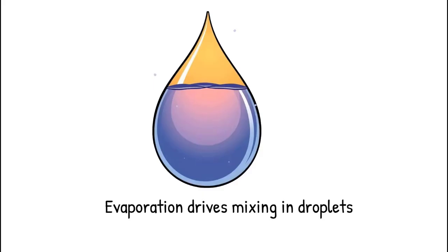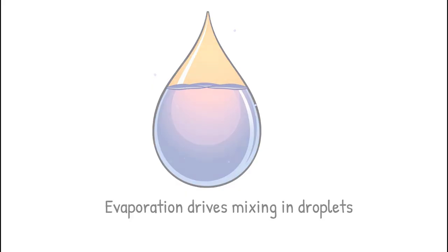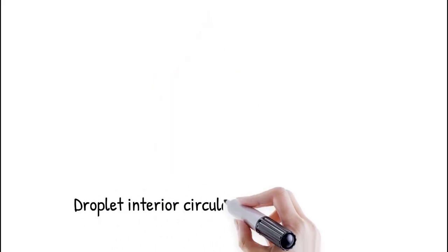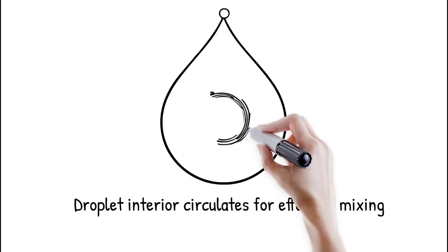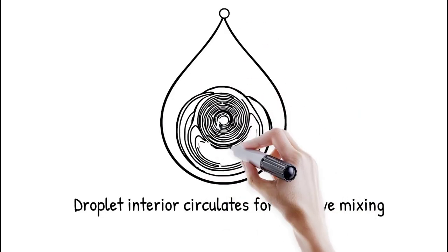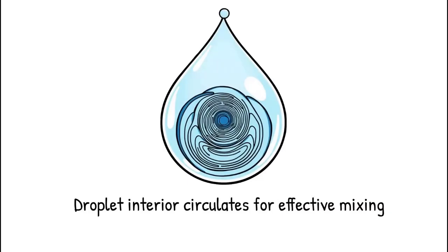Another driver of mixing is evaporation. As solvent leaves a droplet, solute concentration gradients form near the interface. These gradients create density differences, which in turn drive solutal convection. Vapor pressure variations also induce asymmetric flows. The droplet interior circulates in response, mixing solutes far more effectively than diffusion.